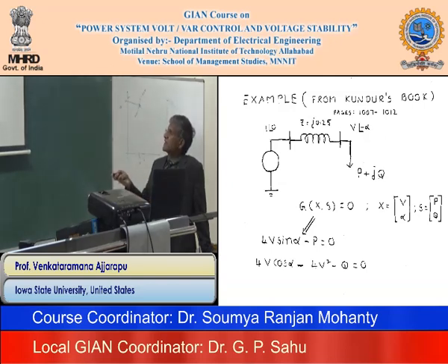So if you do that, basically these are the real power equation and reactive power equation, right? So it's like P equals V1 V2 by X sin delta, and again V square by X minus V1 V2 by X cosine delta, right? The expressions you have, and the same expressions you are repeating here in P and Q. So you have these 2 equations that correspond to the power flow, or this function G, and your X is V and alpha, the voltage and the angle.